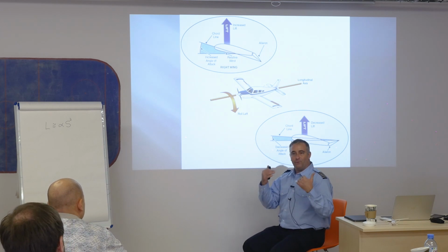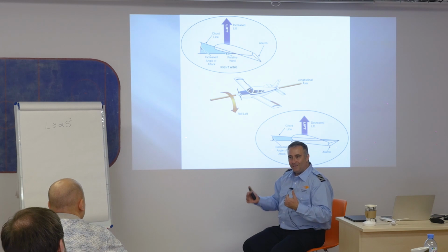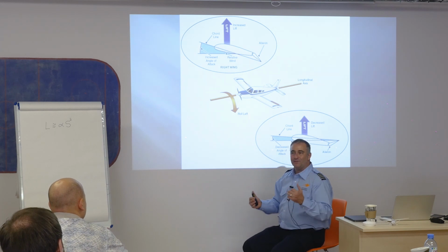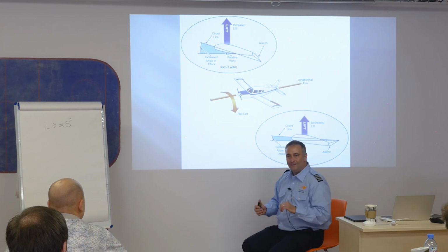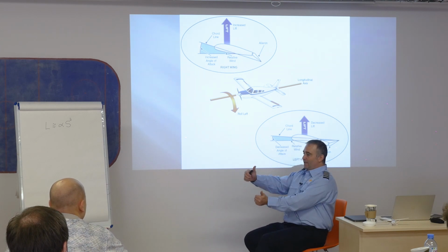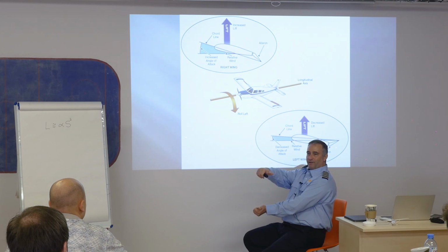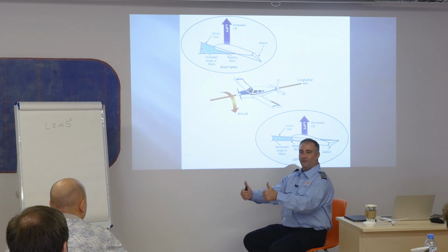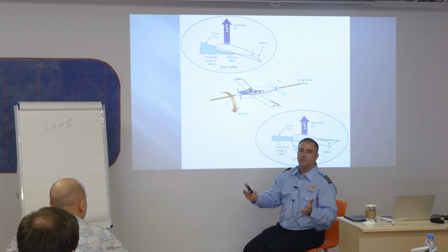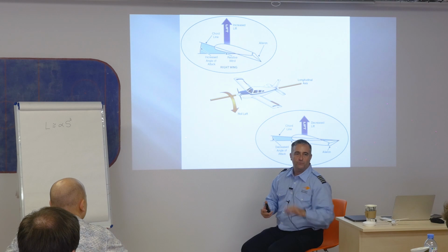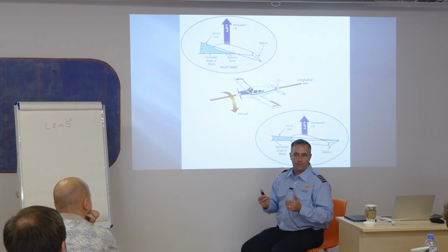But I have to do that. We don't have a yaw damper on this airplane. There are no fancy electronics or anything else, no gizmos. There's not a wizard in the back that's moving this thing for me. So instead, left aileron, left rudder, they go together, and I release them both together. The same thing if you turn to the right. All right? There are more forces than just that one. There's a couple because we have a propeller on this thing that make it interesting.